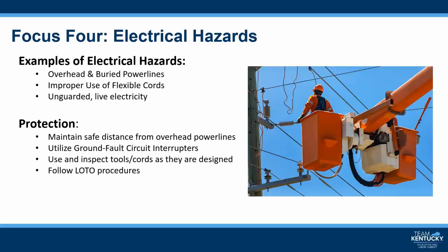Hazards are created when cords, cord connectors, receptacles, and cord and plug connected equipment are improperly used or maintained. To reduce hazards, flexible cords must connect to devices and to fittings in ways that prevent tension at joints and terminal screws. A flexible cord may be damaged by door or window edges, staples and fastenings, abrasion from adjacent materials, or simply by aging. If the electrical conductors become exposed, there is a danger of shocks, burns, or fire. When a cord connector is wet, electrical current can leak to the equipment grounding conductor and to anyone who picks up that connector if they provide a path to ground.